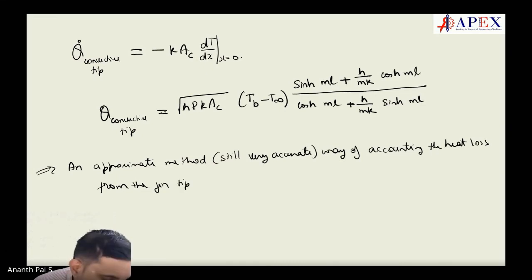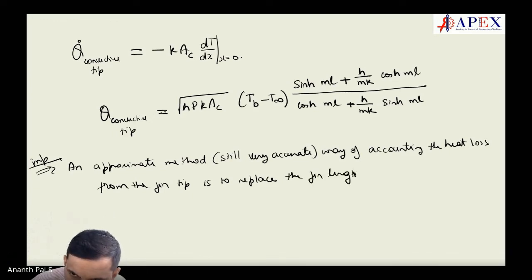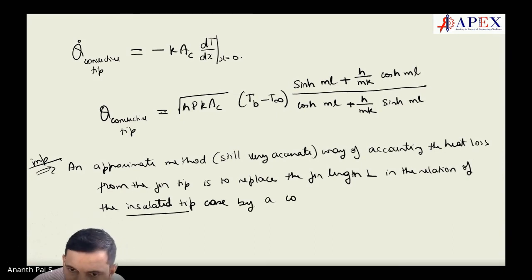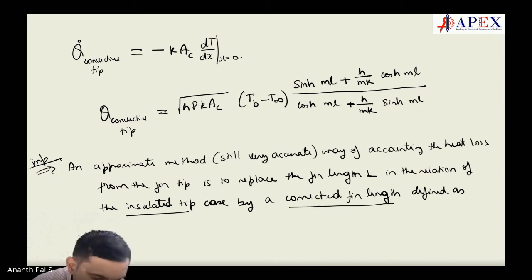Fin tip. This is important, students: it is to replace the fin length L in the relation of the insulated tip case by the corrected fin length, defined as L corrected.